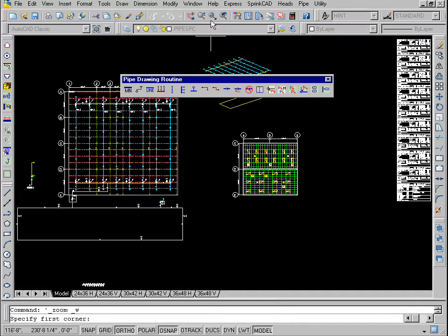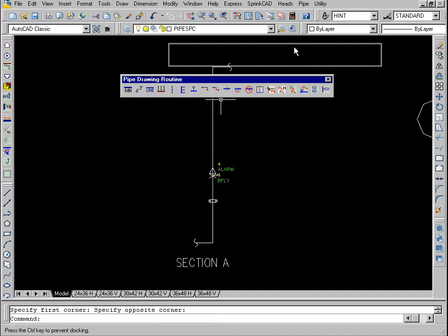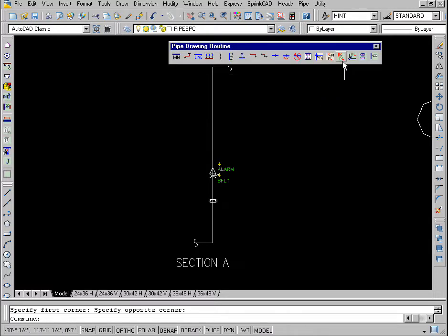Now you can size the riser section. Use multiple pipe size to size the pipes. In this system, the pipe above the alarm valve and the pipe above the stub-up are 4-inch schedule 10. The vertical piece below the stub-up is 6-inch ductile iron, which is the same as the underground in the plan view. Do not size the short stub pieces at the top and bottom.